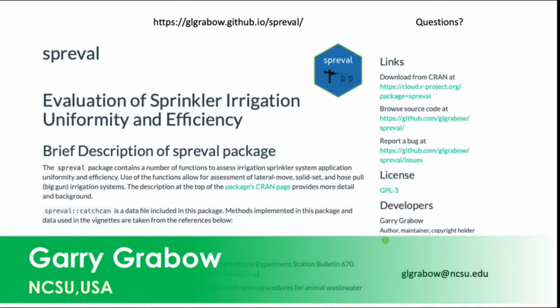Okay. There's the chat. How efficient are water guns or giant long-range sprinklers as auxiliary irrigation in turf fields? What we call big guns here in the United States are usually very uniform, and they can be spaced further apart. So instead of head-to-head coverage, you can go out to like 70% of the wetted diameter and still achieve quite good uniformity because of the pattern that they throw. They go out pretty well up to about 90%, and then they tail off dramatically, but you can get away with a larger spacing between those guns, but they're very good options.